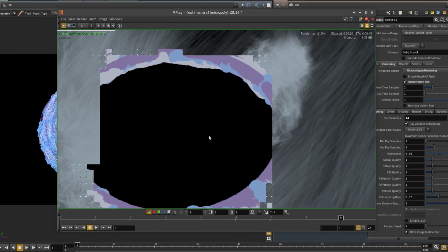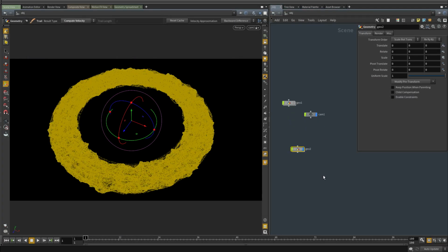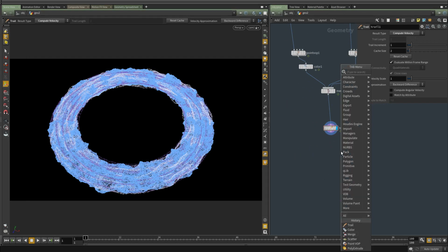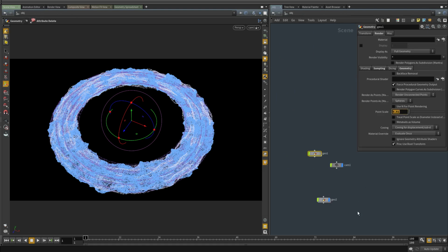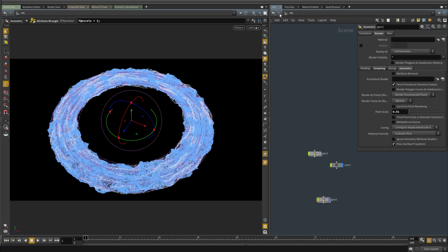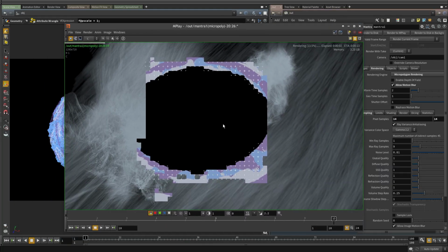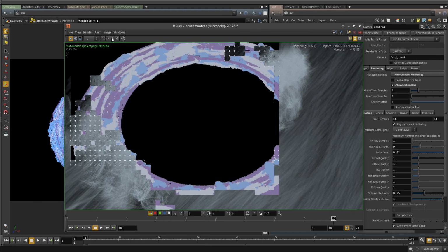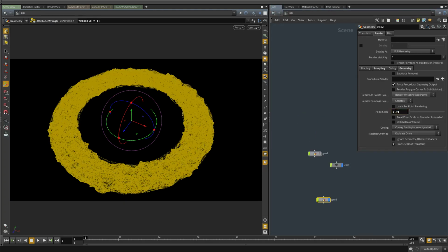So okay, the point size is quite big. So let's do this. Let's create a wrangle node and set this p scale. And again, you don't have to worry about this at this point. So I'm going to set it to 1. And here I'm going to copy this value, which is a multiplier for the scale. I'm going to also turn on velocity motion blur, and trust me, all these things will be talked about in depth later. It's still very big. 10 times.